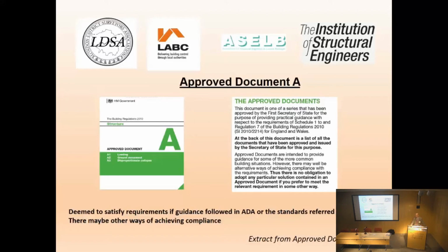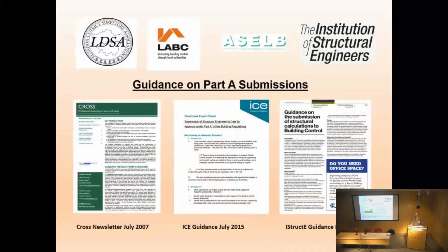We don't get so many structural ones, but there are structural determinations. But quite often when we're dealing with Approved Document B and the requirements under fire safety, there are lots of ways of interpreting the approved document. That only applies to full plans applications. So if your client puts in a building notice, a determination is not open to him.